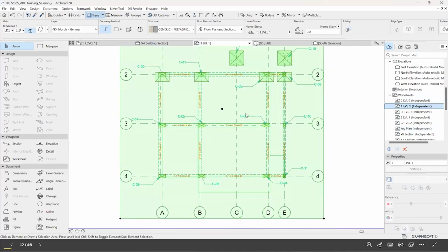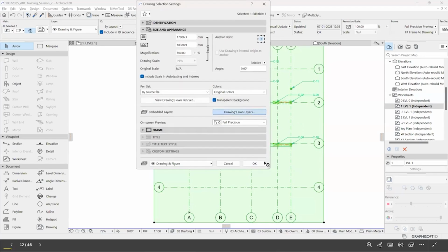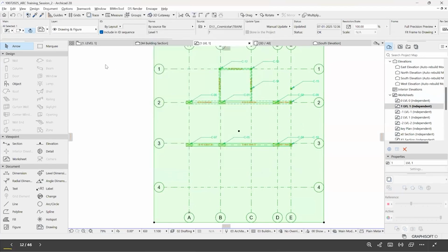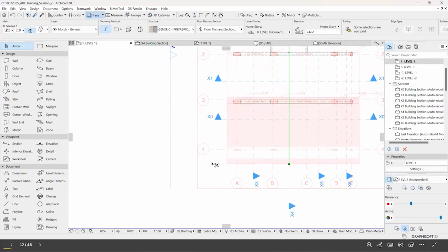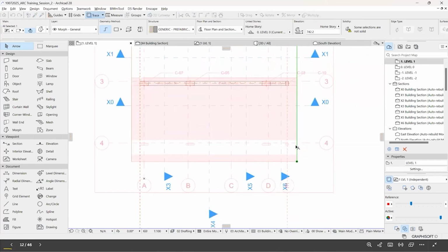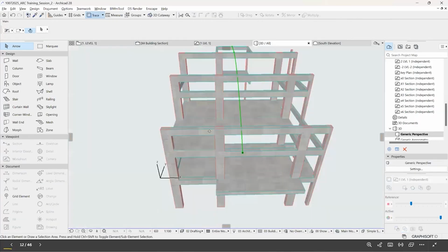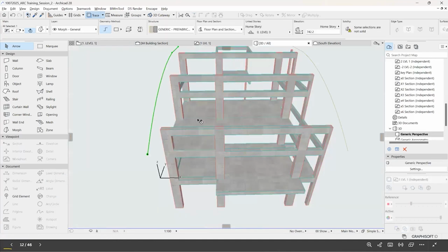If you remember last session, we turned it off. This session, we are going to turn it back on so that we will exactly know from where to where the roof sits. Now I can move this line all the way to here and probably make one more on the other side just for the reference. You don't need to do that if you know the length, but I'm just making sure that I have 2 at the end here.